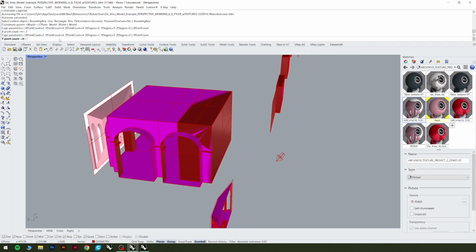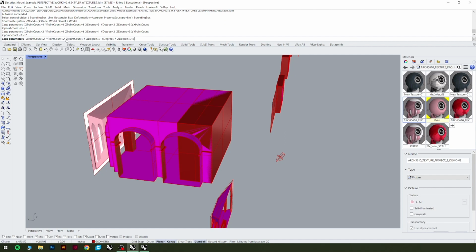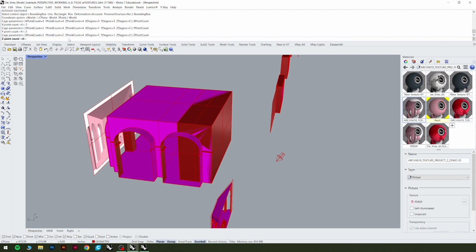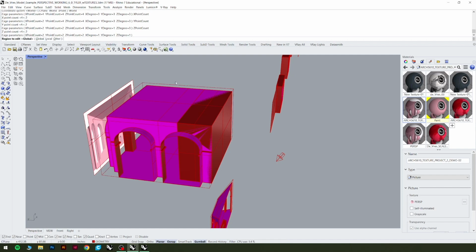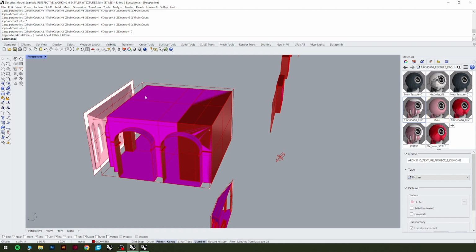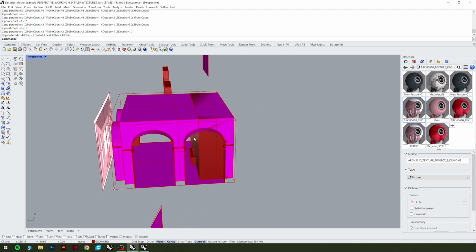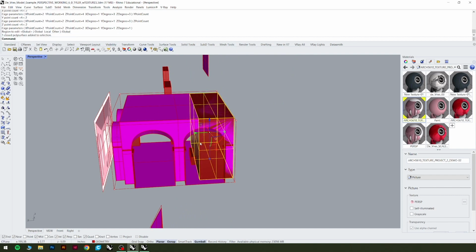Think of a bounding box. There are 2 corners as you go in the X direction, 2 corners in the Y direction, 2 corners in the Z direction. If it was 4, it would be subdividing each face of a box into a grid, and we don't want that. As soon as you change these settings, it will automatically change the X degree and the Y degree and the Z degree. So you can just hit enter from here. Global is my default. If you don't see global right now, hit global. And now we are going to, oh, I just realized we need to hide this bounding box, I think.